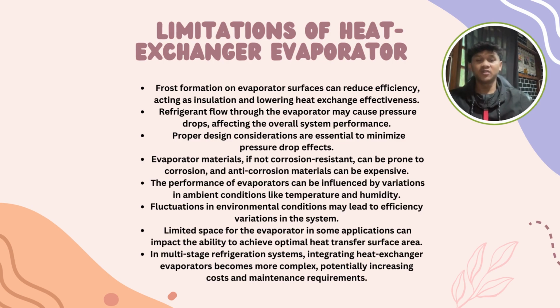Limitations of the heat exchanger evaporator. Frost formation on the evaporator surface can reduce efficiency, acting as insulation and lowering heat exchange effectiveness. Refrigerant flow through the evaporator may cause pressure drops, affecting the overall system performance. Proper design considerations are essential to minimize pressure drop effects.